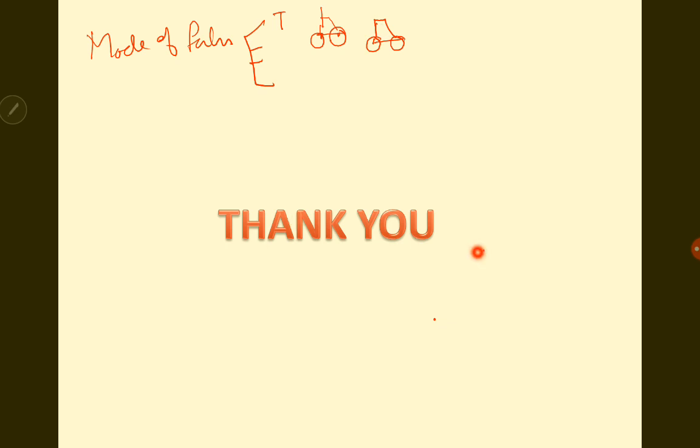Wherever tension comes, there comes a crack, and this crack will reduce the effective area, causing stress to develop. This stress will cause further cracks, and then more and more cracks will reduce the effective area, and so finally the structure will completely fail. That is a tension crack failure. Next is compression. It's a material property basically. If the allowable compressive strength and the developed compressive stresses are within the limits, no problem. If the developed compressive stress exceeds the allowable compressive stress of the material, in that case the material will fail. Next is sliding.